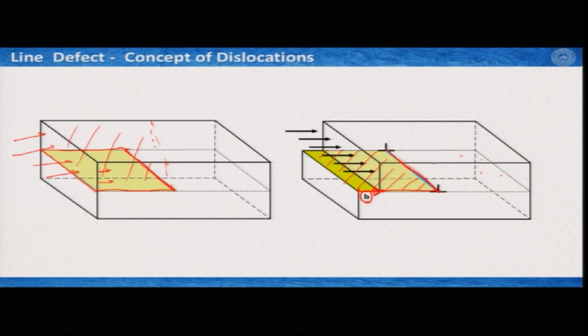Now, because the volume has to be constant, in this segment you might have some rearrangements of the atoms within the lattice, so that it can accommodate this unit vector displacement within itself. So the atoms are arranged accordingly to accommodate the deformation, while the other part is not deformed or disturbed. Now, this line is known as the dislocation line that separates the slipped and non-slipped part.